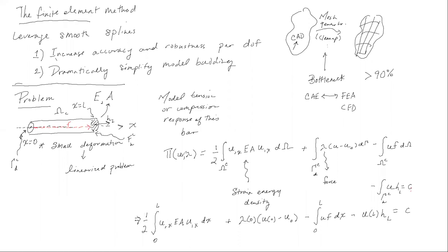All right, and we've already kind of called out that there's something special about the CAD geometry. We're going to need to know where that is, because we're not going to have the tight coupling between our approximation geometry and our CAD geometry. That's one of the ways we're going to dramatically simplify model building up here. That's also another reason we introduced a Lagrange multiplier here.